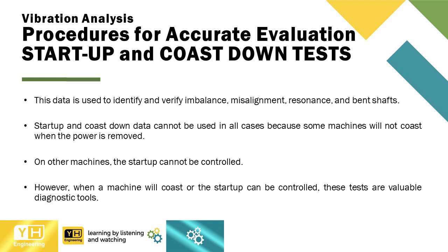Startup and coast down data cannot be used in all cases because some machines will not coast when the power is removed. On other machines, the startup cannot be controlled. However, when a machine will coast or the startup can be controlled, these tests are valuable diagnostic tools.